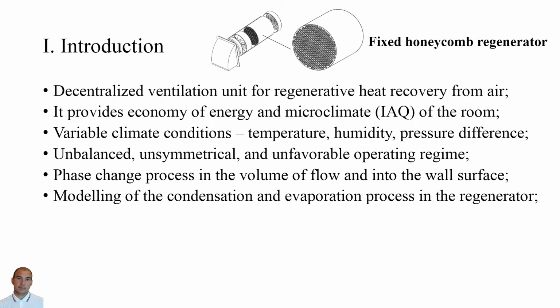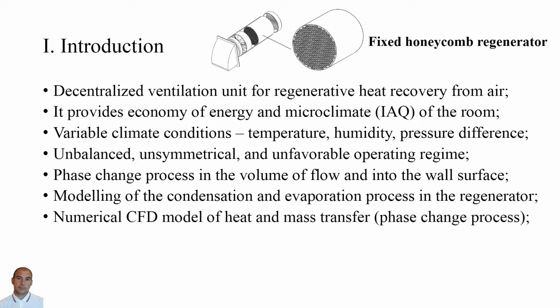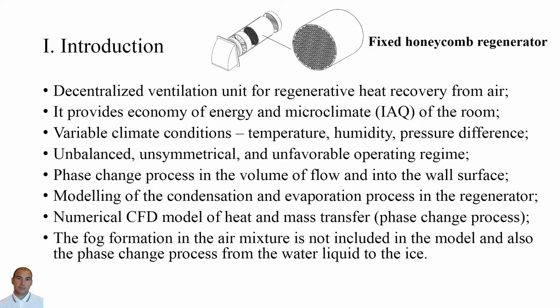For this purpose, an accurate and flexible mathematical model is needed to study the evaporation and condensation phase change process in the counterflow matrix operating with humid air. In this paper, we present a numerical CFD model that contains the heat and mass transfer process of condensation of water vapor of humid air onto the wall surface of the matrix channel.